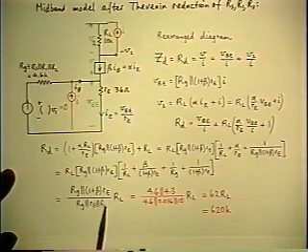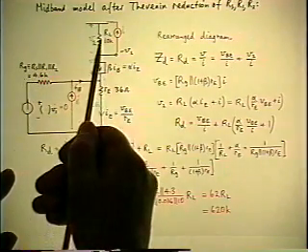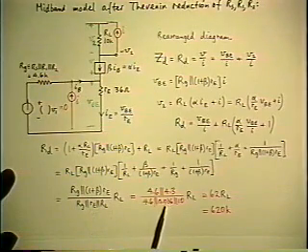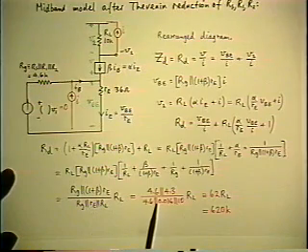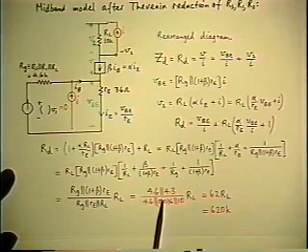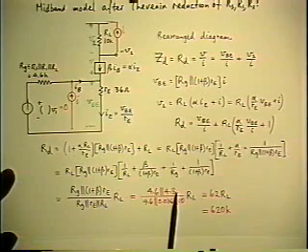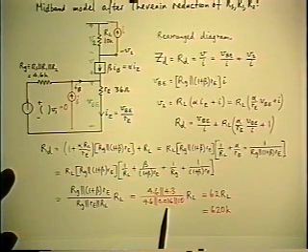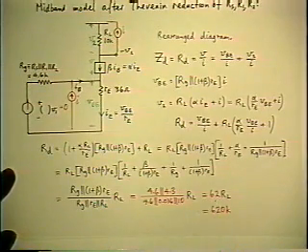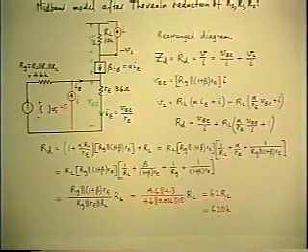When you look at the denominator, it's a triple parallel combination of RG, RE, and RL, and it's dominated by the small one, which is the RE of 36 ohms. The other two hardly make any difference. So the net result is that the numerical value is about 2.2K in the 2.4K in the numerator divided by 36 ohms. That's why the answer is a large number. Since RL is 10K, the RD is 620K.